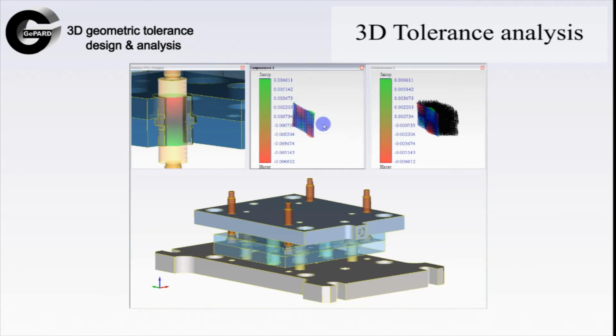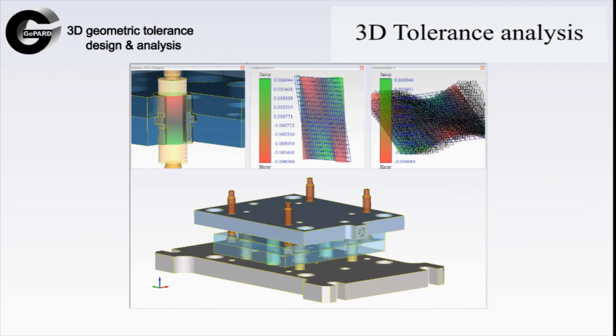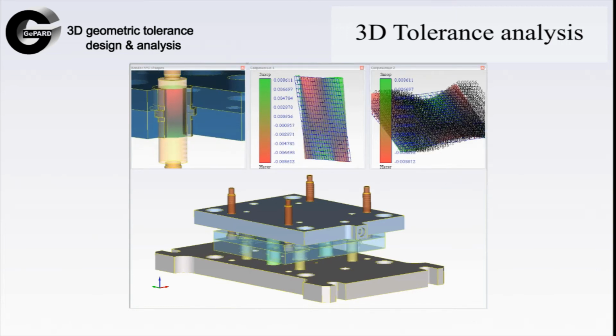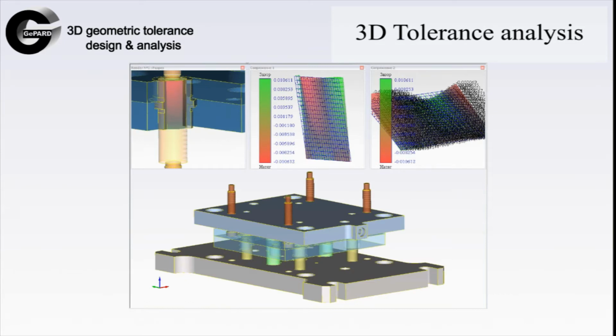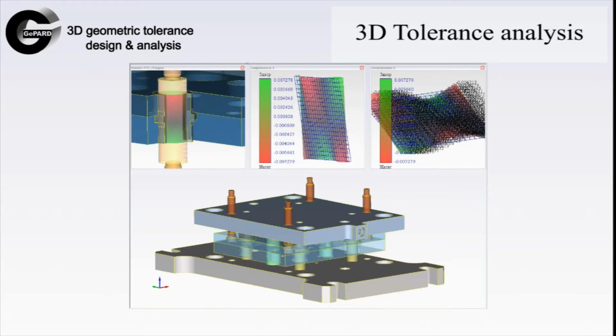A current example shows a movable part of a mold where some tolerances are assigned. We can see the red zone on the accuracy plot for one of the shaft hole joints. It means there are intersections for the shaft hole surfaces in some locations, so assembly is unsuccessful. There is a cross-section of the joint shown in the upper left corner.